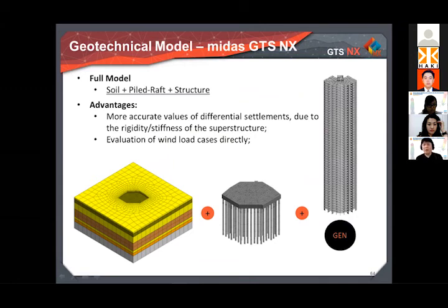Looking at our model, we tried to create a full model, which is the soil plus the pile raft plus the structure building. As was said, it is understood that differential settlement behavior seems to be closer than when using other kinds of models. Another benefit is being able to evaluate different load cases directly, and also wind load.